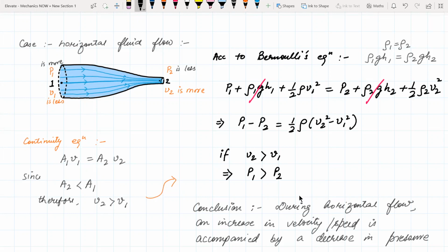Okay, sir. Got it. But if it was already in motion, let's suppose you have a horizontal pipe and there is a motion that was created by some pressure difference initially, that motion will remain there. If you look at point 1 to point 2, there is no pressure difference here, but the motion was initially there. But if you want to create a flow of a fluid that is at rest, there you need to create a pressure difference. So pressure difference in fact acts as some sort of an accelerating impact. Are you understanding? Yes, sir. Got it. Thank you, sir.